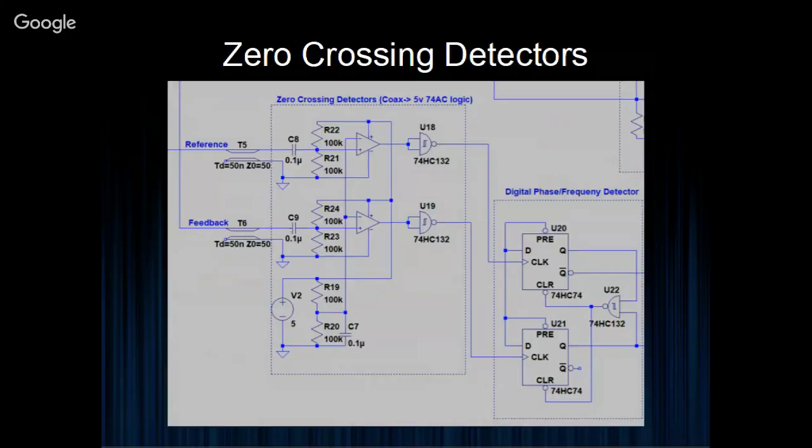So if the presented signal causes this point to swing either side of that reference, it's going to register as being above or below it, and put out a 1 or a 0 respectively for that zero crossing event. Comparators are relatively expensive to get high speed. If you're talking about tens or hundreds of megahertz, you're going into sort of $5 to $20 something for a comparator, which is a bit ridiculous. And that's only because they're expected to operate very, very quickly.